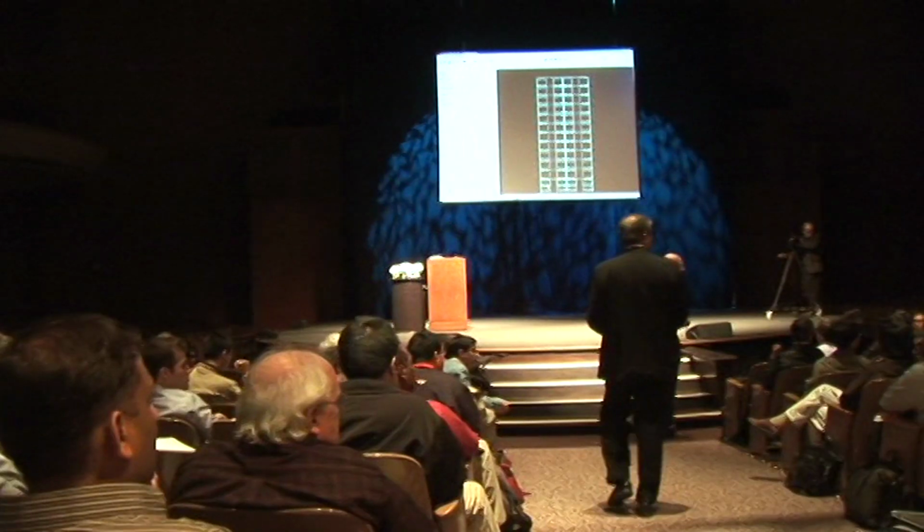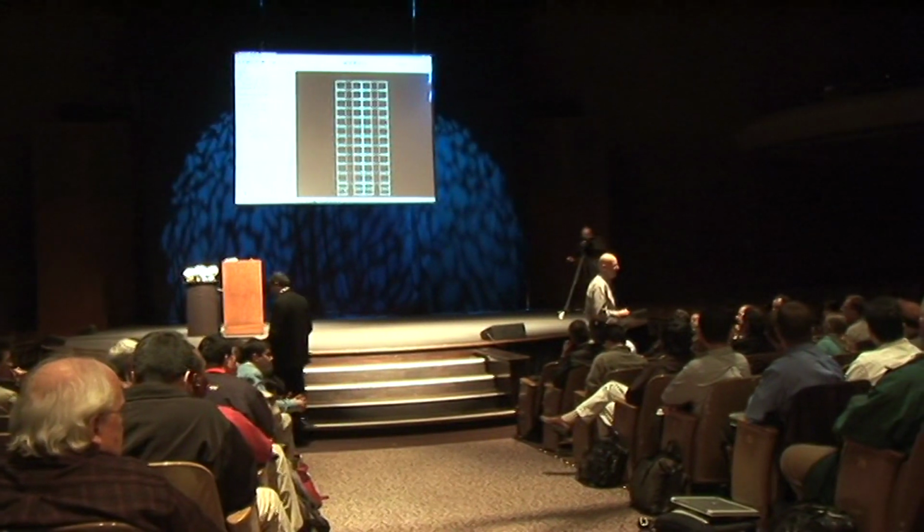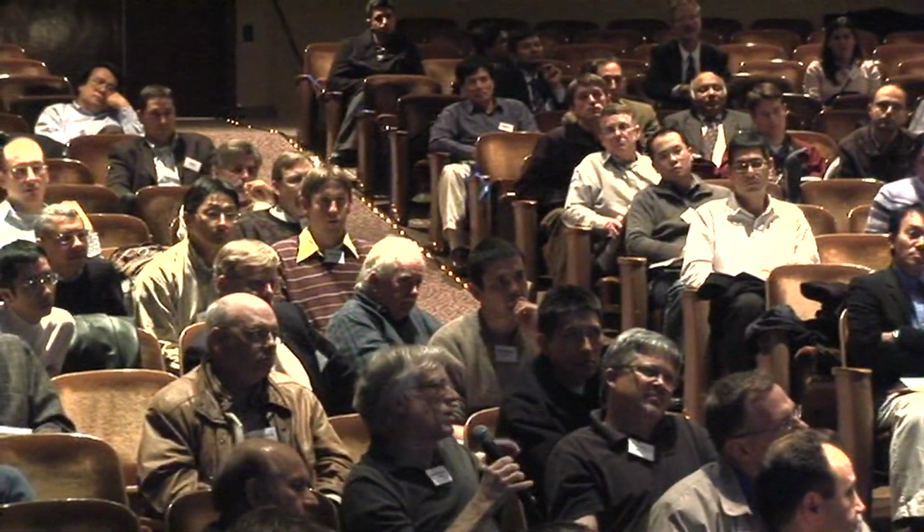Professor Powell, to your left. Just to clarify, the force diagrams that you were showing, were they plotted in the direction of the coupled wall or the uncoupled wall? Oh, they were in the solid direction. Yeah, the uncoupled, the short way. I could have shown you some in the other direction, actually. What happens in the other direction is that the coupling beams get clobbered and nothing else much happens.